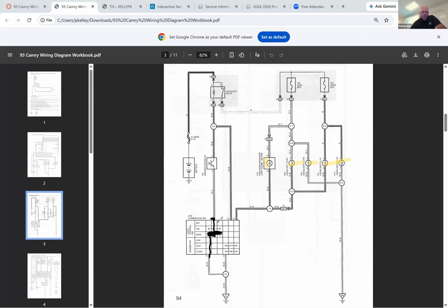So if now we turn the headlights on, now 13, I know it's tiny to see, 13 is right here. 13 will be connected to 11, which is right here, okay? That's the detail a lot of people miss. Then from there, we change over to highlight. We're going to do red off the battery, red to the relay. Remember, that coil is a load, so we shouldn't go through there, but red does split over here.